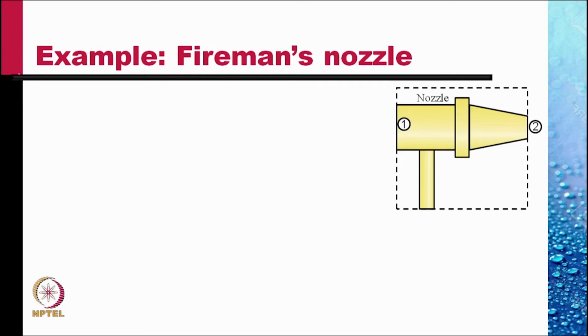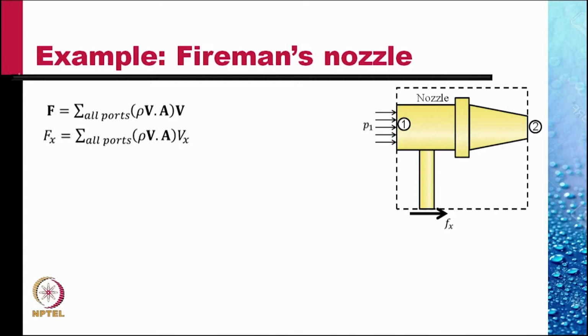This is the control volume that we take. We draw all the external forces on this. There are only two: the gauge pressure P1, and the force Fx. There is atmospheric pressure all around, but atmospheric pressure all around leads to zero force. A uniform pressure all around a volume leads to zero net force. So the equation